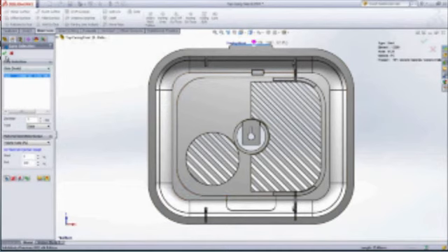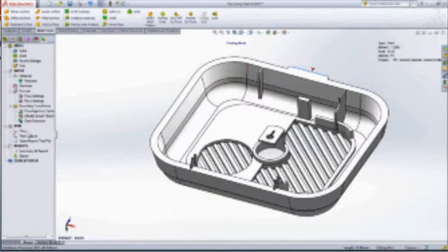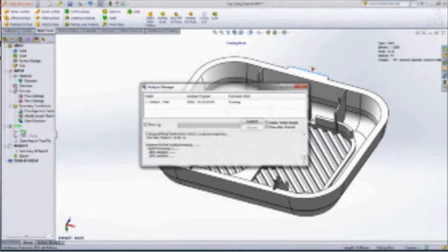After meshing the model, selecting a material, and picking the gate location, we're ready to go and we can now run the analysis. As a mold designer, and to get even more accurate results, we can also change parameters such as the injection molding pressure and the mold temperature.